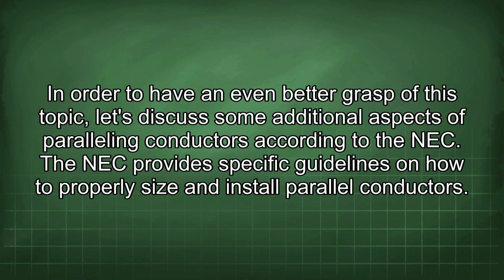In order to have an even better grasp of this topic, let's discuss some additional aspects of paralleling conductors according to the NEC. The NEC provides specific guidelines on how to properly size and install parallel conductors.